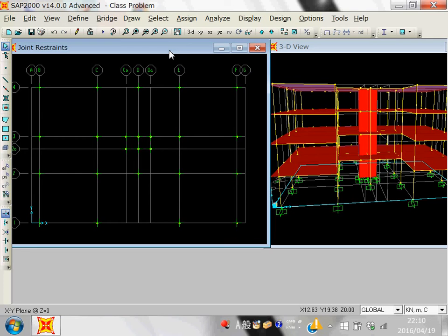Partition walls we do not add because partition walls do not have any role in taking the load. You understand? This is the main skeleton of your structure which is going to take the load. Anything which you will add later on it will be the extra load, and you have already considered it in the form of wall load and live load. Okay? So whenever you see any construction, you see this type of building. This is the main load carrying structure.